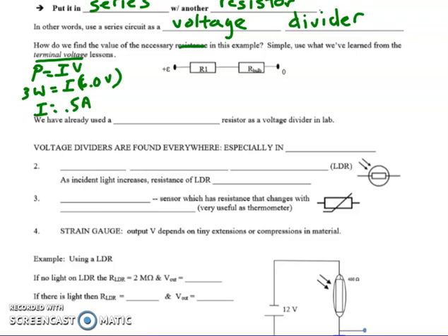All right, so what I'm going to have here, if I haven't made this clear, is this EMF, that's my 9 volts. Across that 9 volts of potential is R1 and my bulb. I know that I want the bulb to be 6 volts. So we can also use the KVL, the loop rule, that says the drop across here plus the drop across here has to add up to 9. So if I want a 6-volt drop here, then that means I want a 3-volt drop across there. And if I know that I get 1/2 an amp in the circuit, because that's what the bulb is going to work best at, then I have that piece of information.